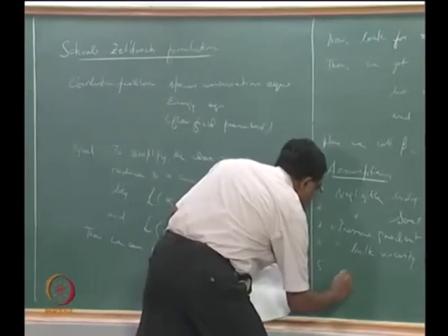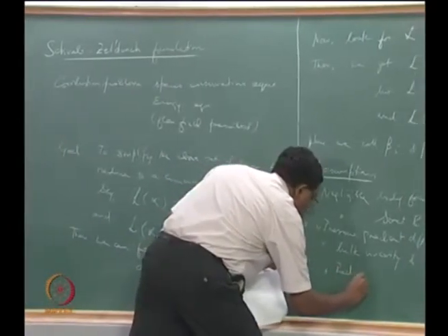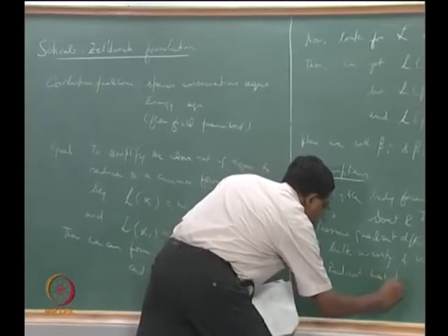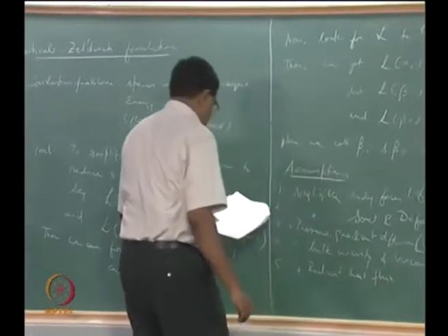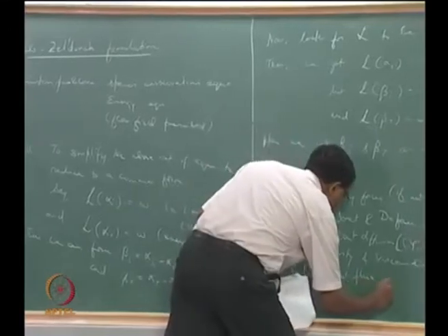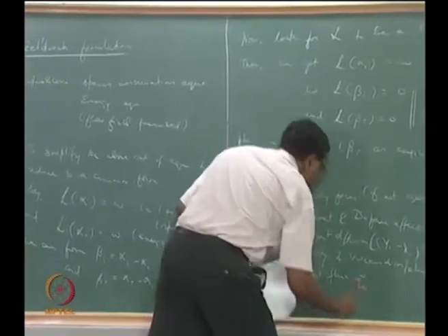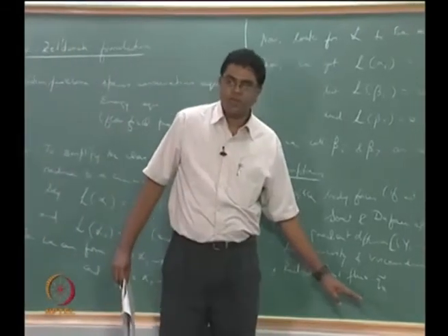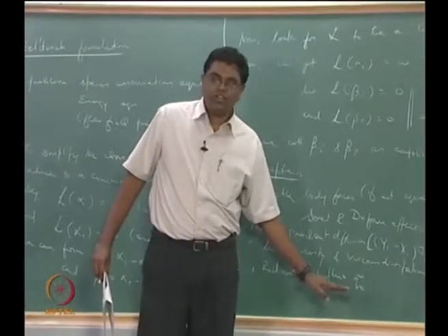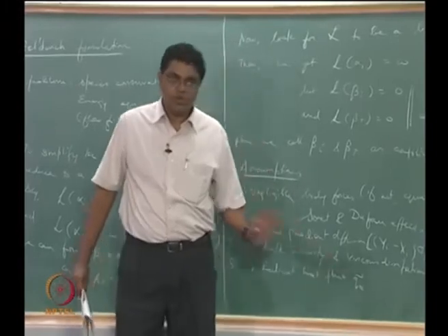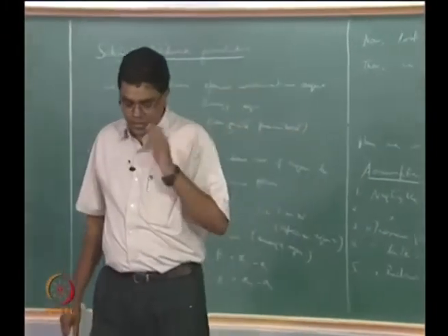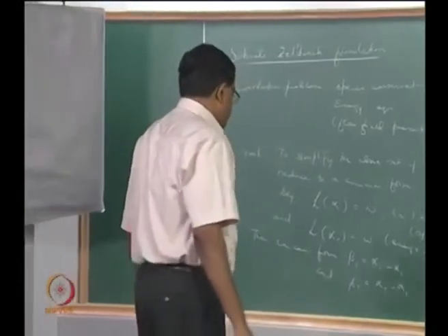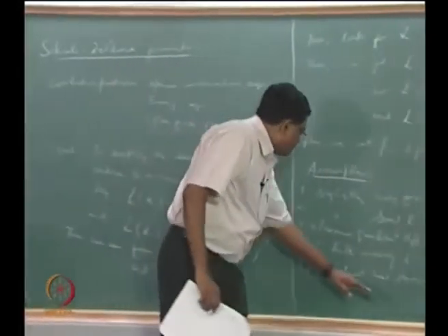Negligible radiant heat flux, right, the QR vector. Now of course this is going to be a nonlinear term if it were present, so you are going to have a T to the power 4 and T is an unknown, so you are now looking at a nonlinear effect there, so try to get rid of it, okay.